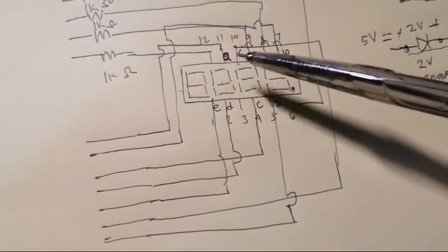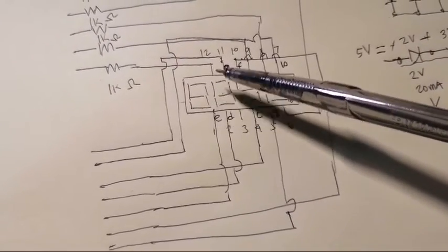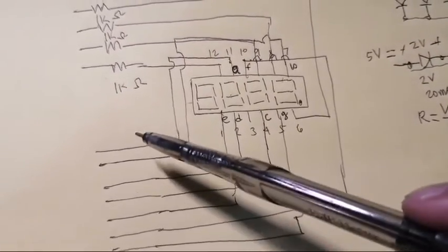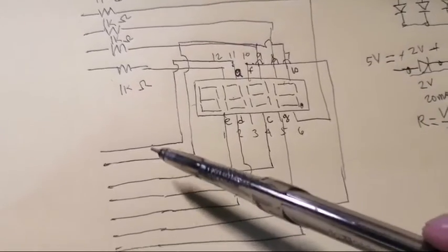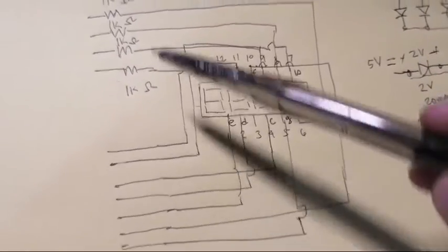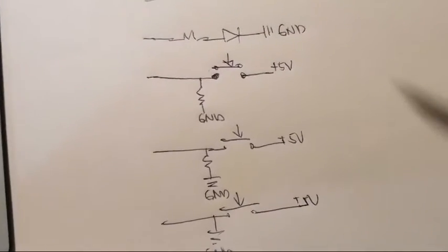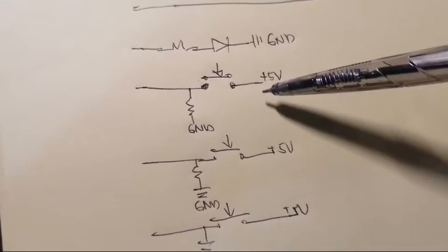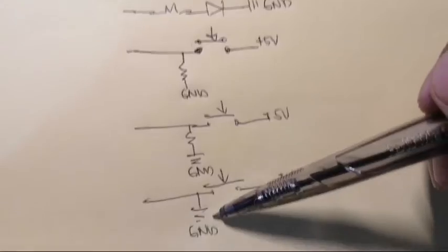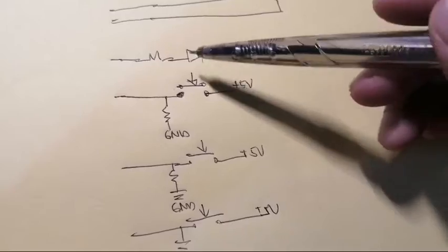The 3 other segments will be idle or no power. So this is now the connection from the 7-segment pins. So this will be connected to the Arduino pins. We will see later which pins of the Arduino we will be using for all of these pins and these 4 pins. Here you can see the LED, the 3 push button pins and the pull down resistors. This one is the limiting resistor for this LED.